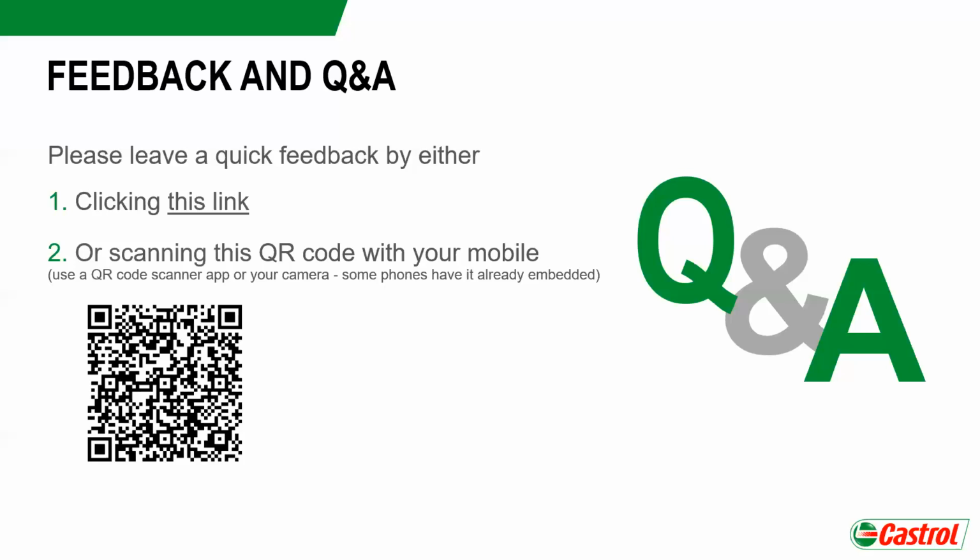And if it's a coal grinding mill, it could be exposed to the elements, which might be -10 in winter and +30 in the summer. So you need something that has a good viscosity index. Optigear Synthetic PD ES, I believe, Daryl is on the call still, goes up to 680 centistokes. Yes, it goes up to 680.